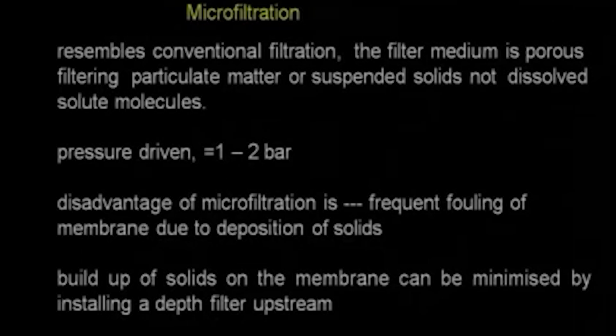So what do we do? Once you do this type of membrane filtration and you want to get rid of the concentrated slurry, sometimes companies will resort to solar drying. That means they will have open space, and maybe they will have long plastic surfaces on which the slurry is put in, and water will get dried because of the heating, and the solids which you get, you collect and use either for further processing or disposal or landfill or animal feed, whatever you think of. So you need to resort to this type of solar heating.